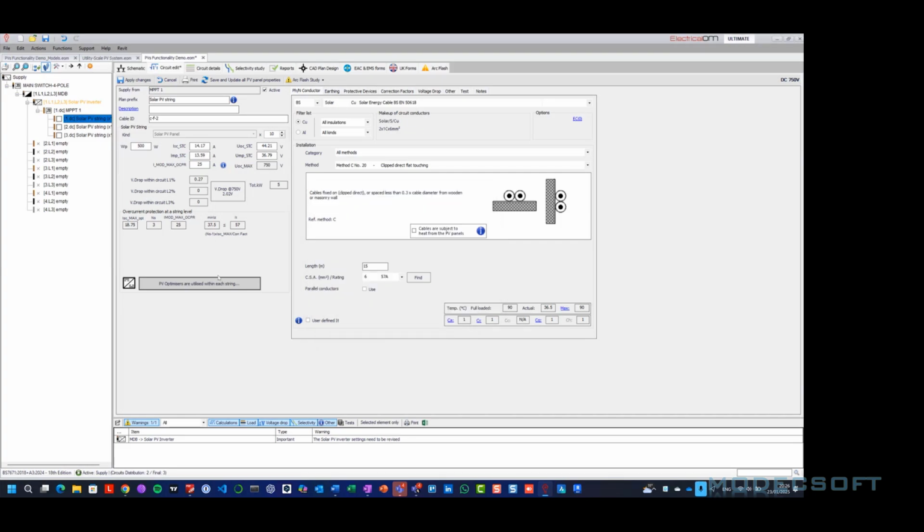However, because we have optimizers, we don't allow reverse currents to flow through towards our modules, so there is no need to apply the mod max calculation checks. But for our cable string sizing, we need to apply these calculation checks to make sure that the current carrying capacity of our cable is adequate to withstand any reverse currents that may occur at the secondary side of our optimizers.